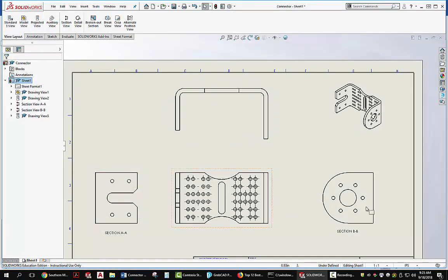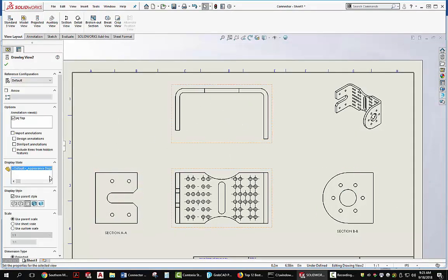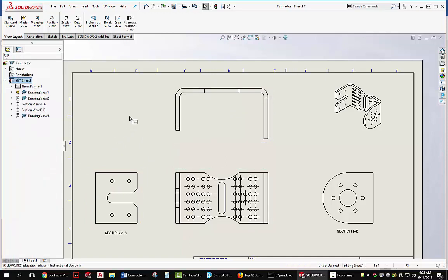So I'm going to leave the left view and the right view the way they look. I'm going to come up here and go to the left, and I'm going to select hidden lines, and that's what it would look like if I showed all the hidden lines. Now you might decide that this also is too confusing to be helpful, in which case we can go back to this, or we could delete certain hidden lines and leave the others in. Because of the large number of holes in this, what I think I'm going to do for this video is just leave them the way they are.